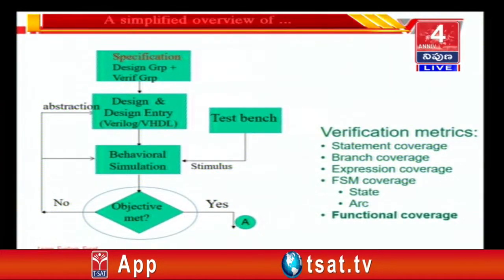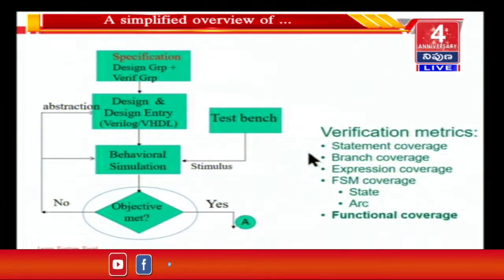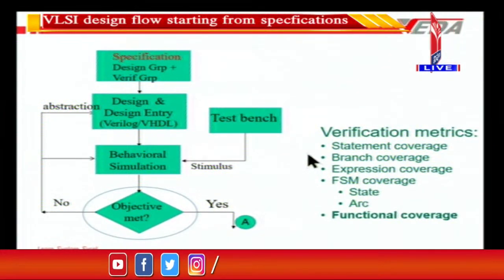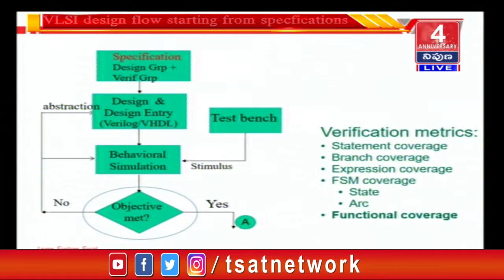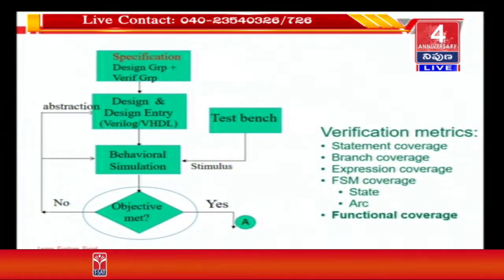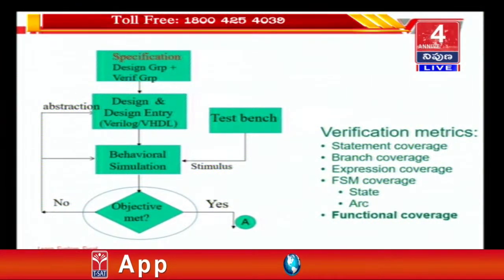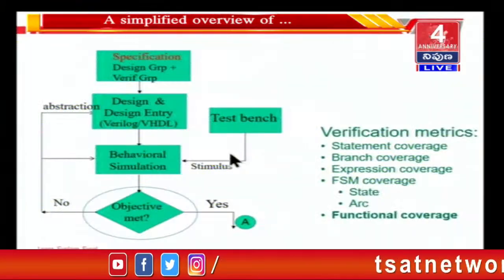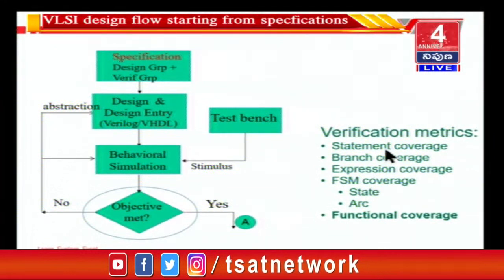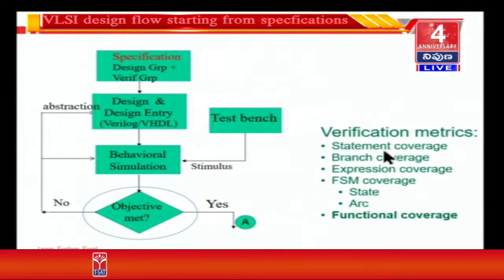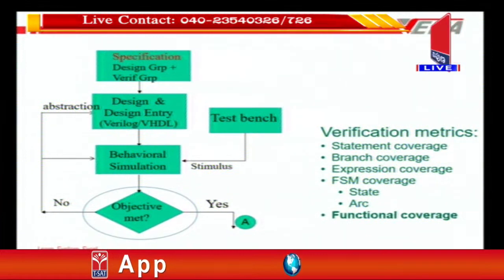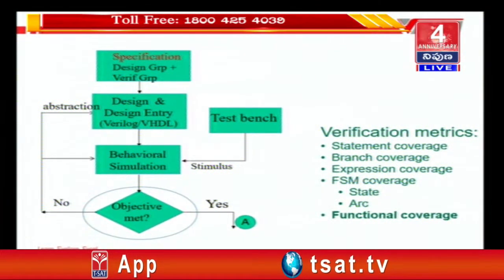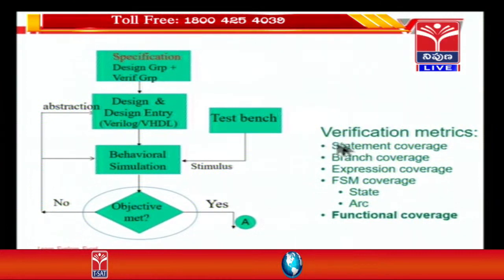You have to include an option called coverage option when you run the simulation, so that the simulator will take slightly more time, but it will gather information about which statements are executed in the design code. The design code needs to be exercised completely by the test bench. So, that will let you know the statement coverage: how many statements are there, has each statement been exercised at least once or not. That is the statement coverage.